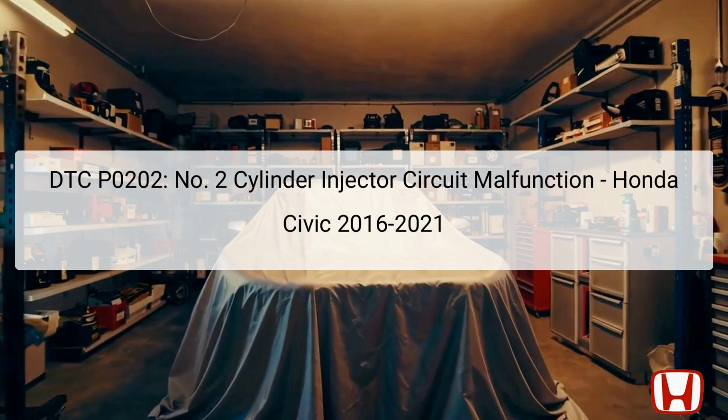Diagnosing this issue starts by verifying that the correct DTC is present and distinguishing whether it's confirmed or pending. Additionally, when examining the fault, it's important to check for stored codes like P0560, P068A, and P068B that may accompany P0202. These must be resolved first to ensure accurate troubleshooting. Thus, understanding the interplay between various components in the fuel injection system becomes vital for successful repair.